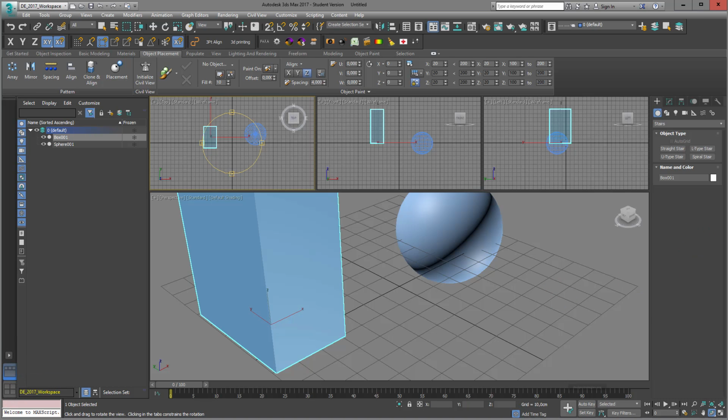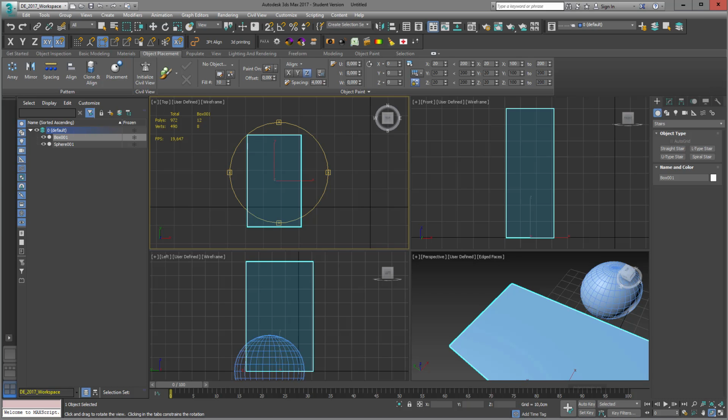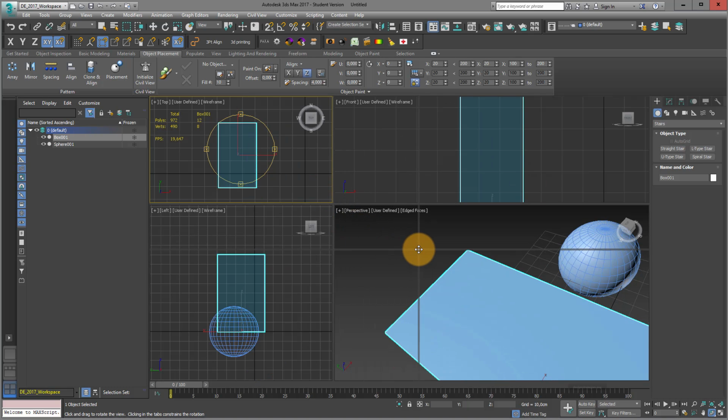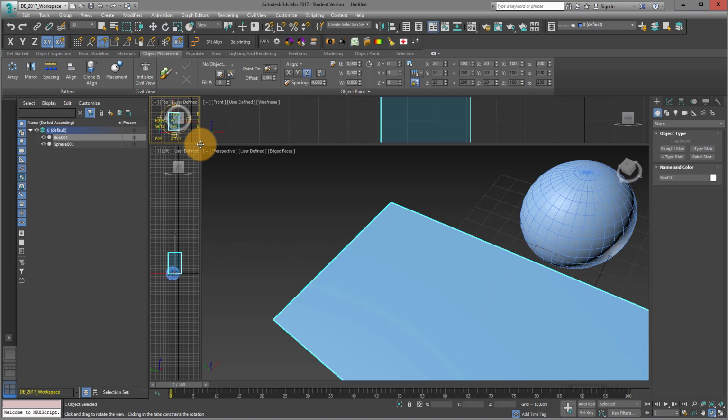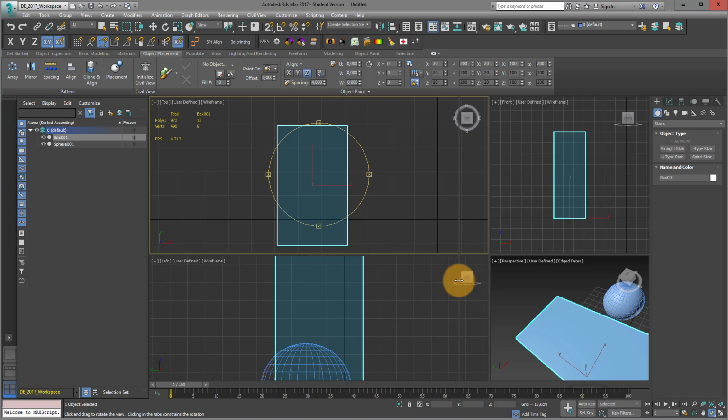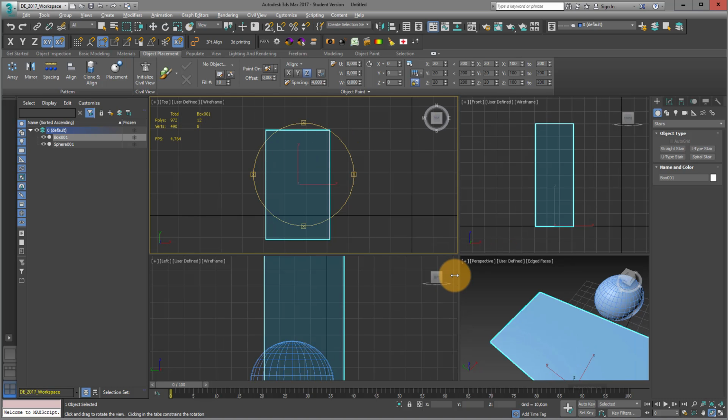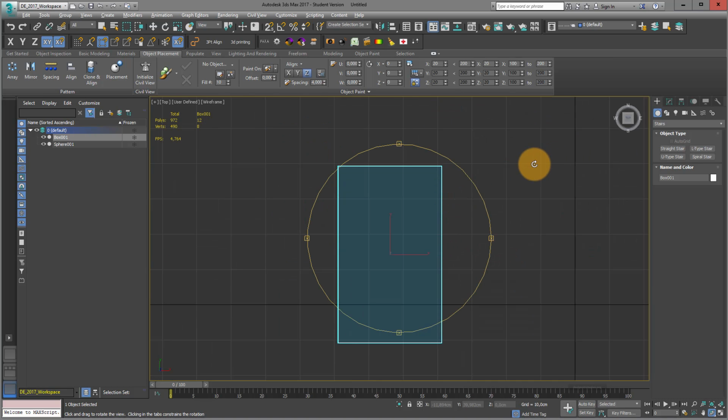You can also change the viewport by moving these edges. I just grab this with my left mouse and expand a part and make the other smaller. I use this quite often. I again go into Alt W, and what's also quite handy is this view wheel.